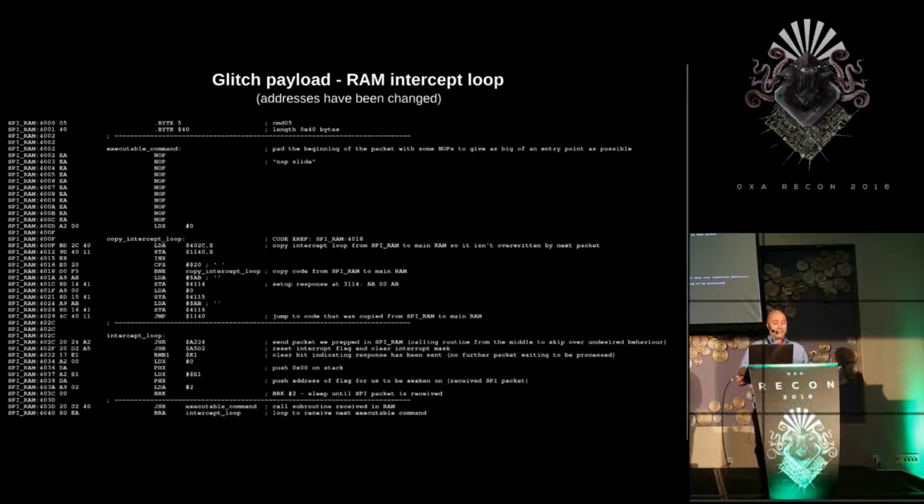So my strategy is to send code to the chip, where it goes into RAM, then glitch to cause an instruction to be misinterpreted, hoping to cause a jump into the area in RAM where my payload sits. To try to maximize the chances of success, I looked through the ROM code for multi-byte instructions which, if broken up, contain within them a jump opcode with a destination that should lead to where my executable payload is placed. Since the ACP has a single address space, this gives really a lot of opportunities for glitching to cause execution to reach the code payload.